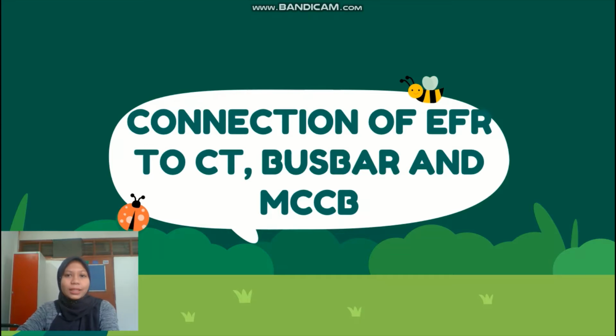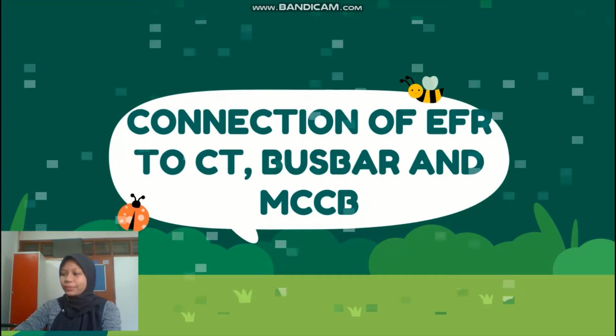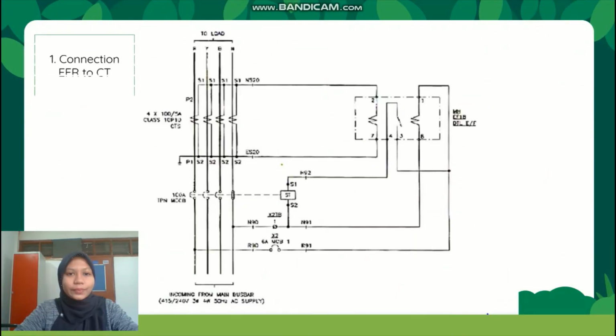Second question, connection of EFR to CT, busbar, and MCCB. Okay, first, the connection of EFR to CT. For CT, pin number 2 will connect to the input supply of the CT, while pin number 7 is connected to the ground.